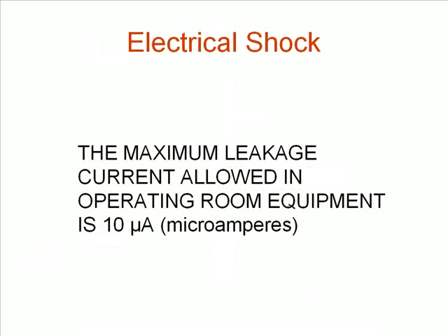That also explains an anomaly that many of you have observed over time, that the wires in some of this electrical equipment are very short. And you say, well, why do they make the wires so short when I've got to move the equipment over to plug it into the wall? Why not have longer wires? And the answer is because the manufacturer wants to keep the leakage current down, and the way they do it is keeping the wires to plug in the wall very short. Of course, then you have to add an extension, and then that's potentially a problem, but it's not the manufacturer's problem, it's your problem. And so it allows them to get by regulatory authorities with relative ease.